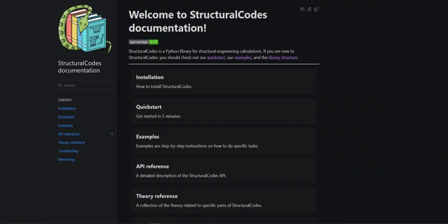So the function call to add reinforcement basically takes the geometry, adds a point to a given coordinate, and this point is assigned the reinforcement material, as you see here. And we do it twice, so we have 2 bars in our cross-section. So now the geometry is no longer a surface geometry, but it's a compound geometry. It's a compound of a surface and 2 points.